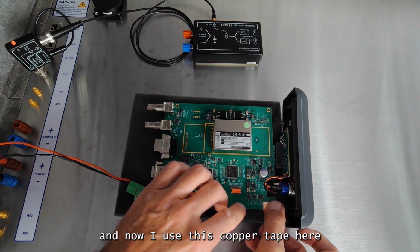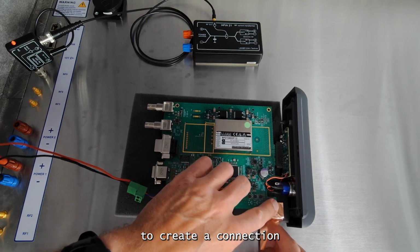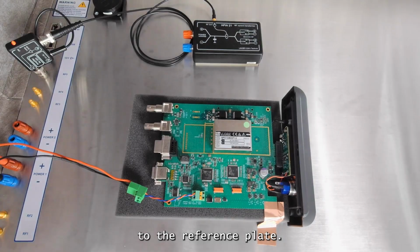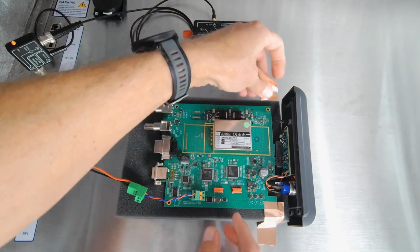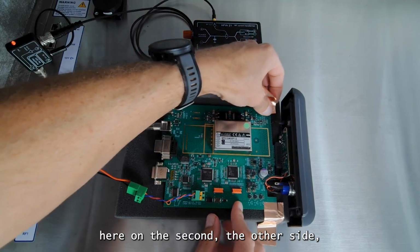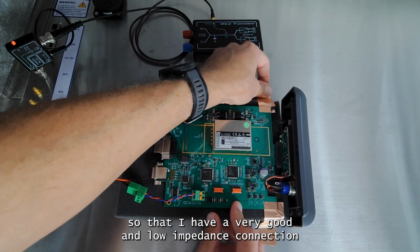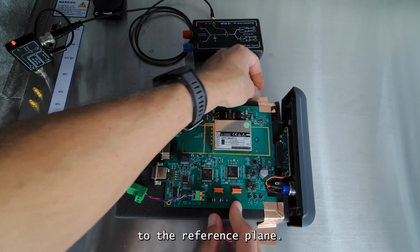And now I use this copper tape to create a connection to the reference plate. And this I do also on the other side, so that I have a very good and low impedance connection to the reference plane.